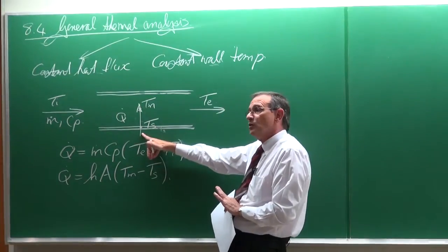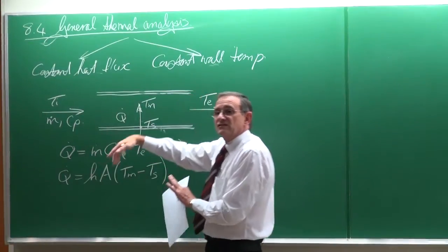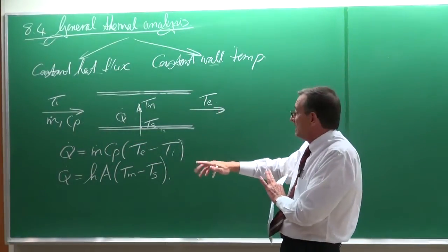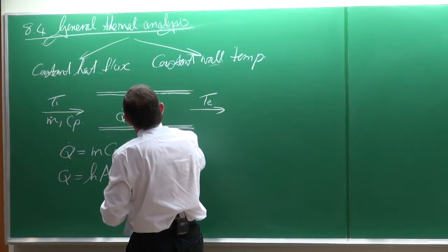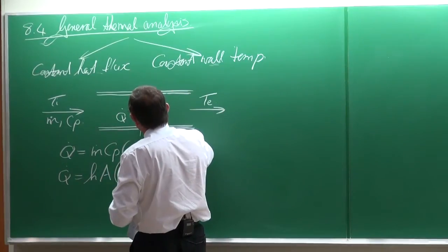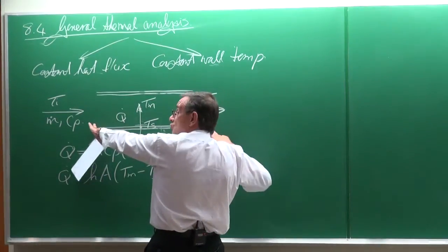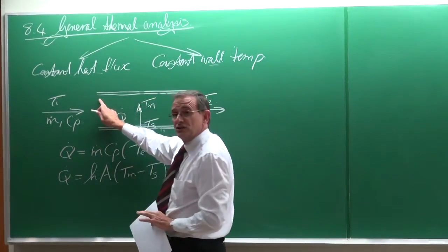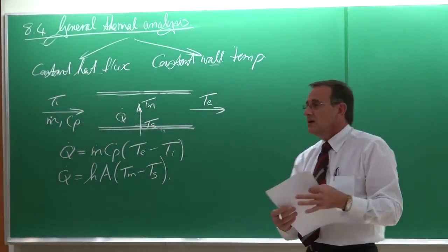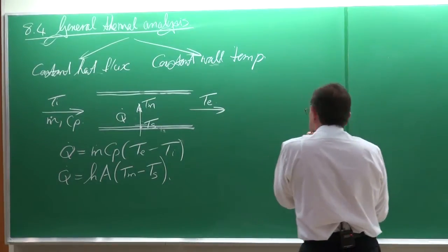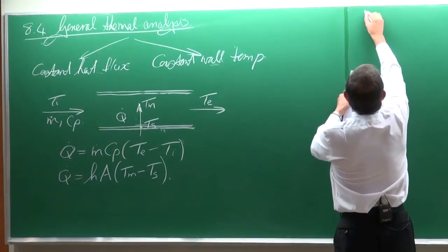However, remember what I've explained to you yesterday with the heat transfer coefficient: at the inlet it is much higher, as the flow is still busy developing. So if this is a very small area, like that's the area and we've got the heat transfer coefficient at that specific position, then that would be accurate. However, if it's for a very long tube, where the heat transfer coefficient is not constant, we need the average heat transfer coefficient. Okay, so think of that. Now let's look first at this case, the constant heat flux case.